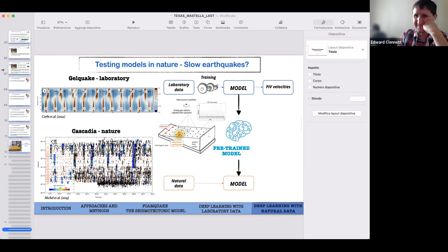How did you decide the resolution for the PIV gridding, or the grid increment? Because it's sort of arbitrary when you process the PIV data, and I'm doing that myself, so I'm curious what you did. Yeah, so you mean parameters like the overlapping, the number of pixels that you use in the cross correlation, things like that?